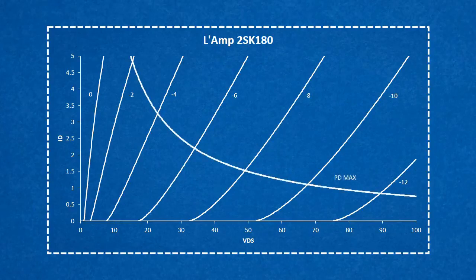Next, we'll draw a line through every voltage and current point at our selected power dissipation limit. In this diagram, the limit is at 75 watts. When we choose our operating point, we'll keep it on or below this line, or risk damaging our transistor.